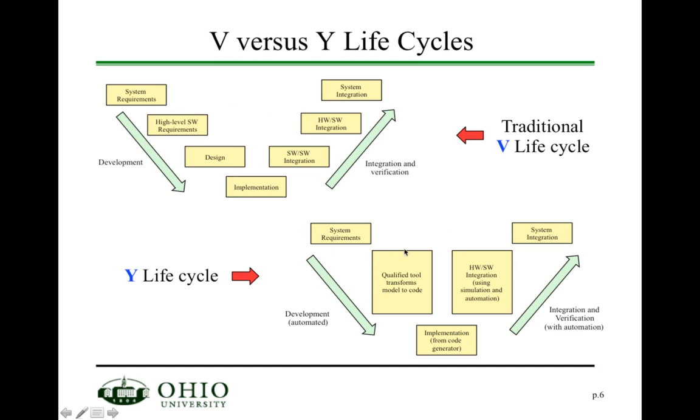So you get a big chunk that represents all these requirements. And a lot of these tools can then take that model and convert it to code. In Simulink, there are tools like Embedded Coder or Simulink Coder that take your Simulink model and turn it into a piece of source code.